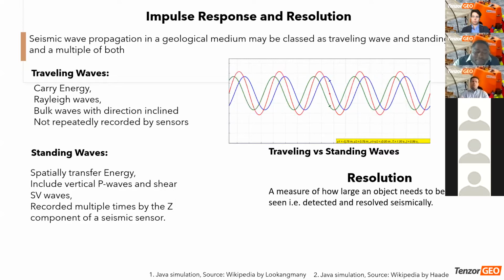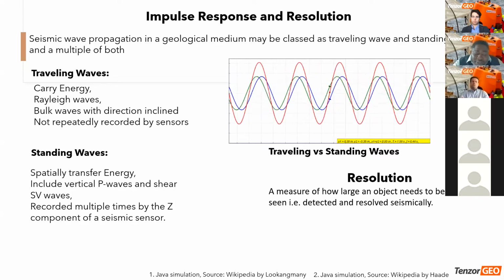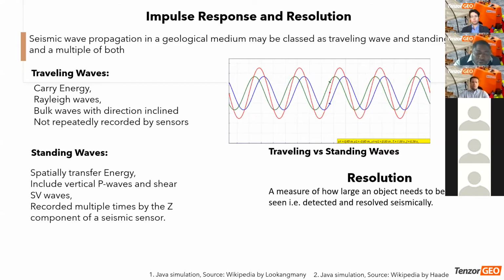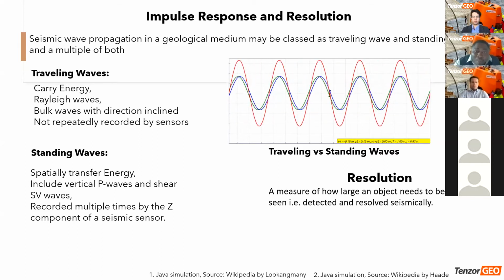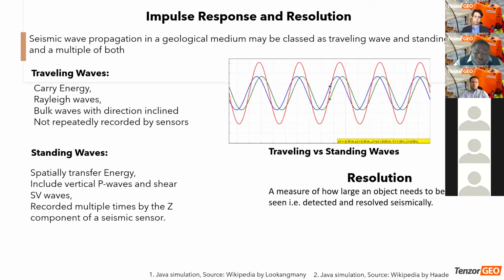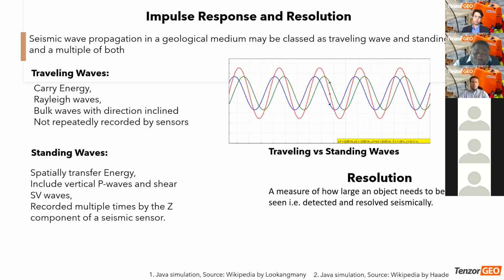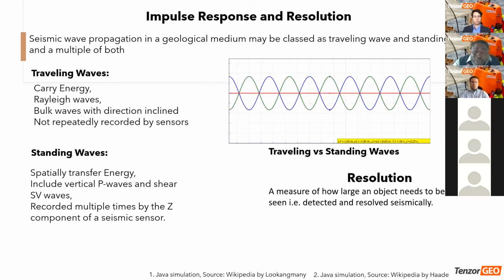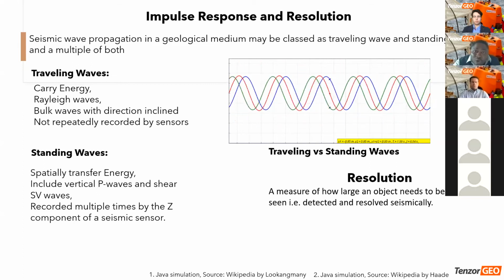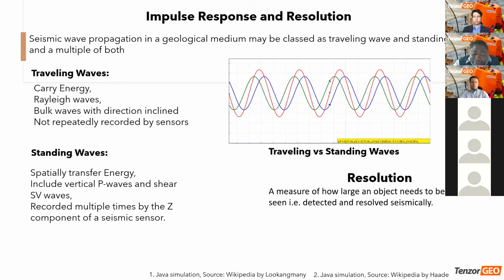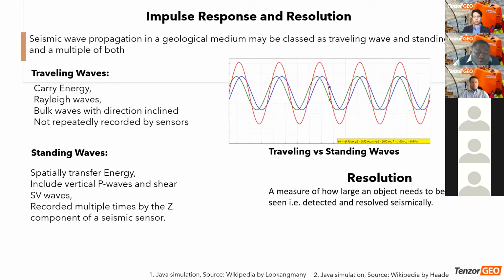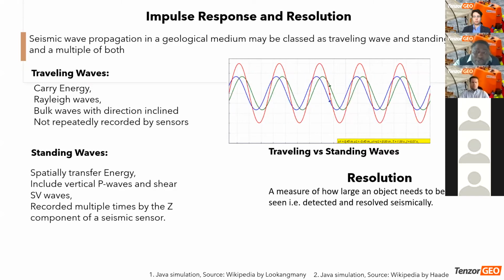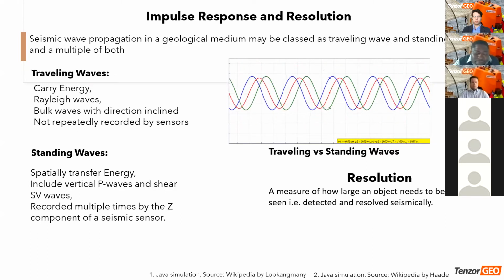The impulse response of a homogeneous media with one thin layer of lower impedance has a modal spectrum structure, which also has what we call spectral peaks. In other words, the impulse response will have multiple occurrences of waves or peaks. And the peaks that occur the most in the spectra indicate the values or the zones of interest.